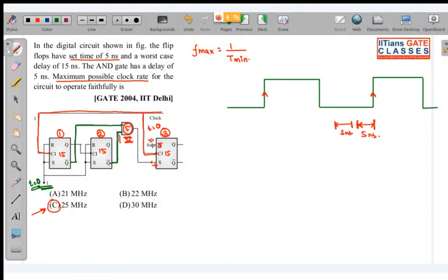But here in this case, one of the inputs was depending on the output of the AND gate. So that is why I was worried about setup time, that it might transition over here. If this was also fixed from T equal to 0, I wouldn't have worried about this setup time. So that is why I am not worried about setup time in these 2 flip-flops.